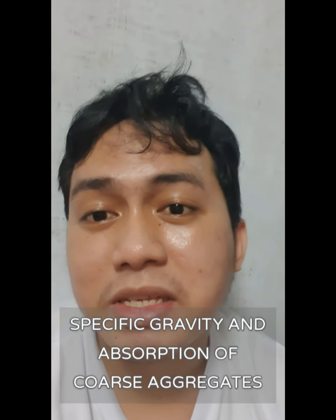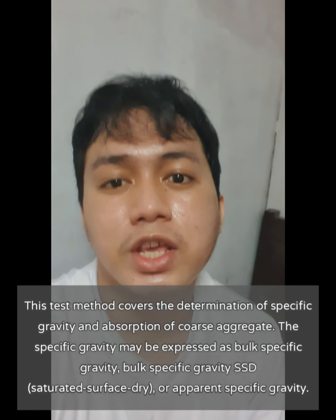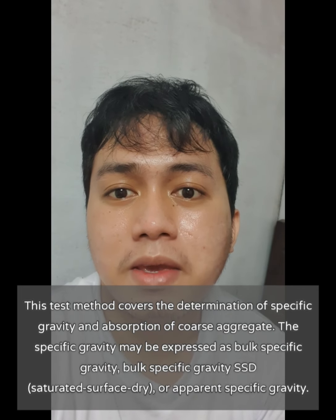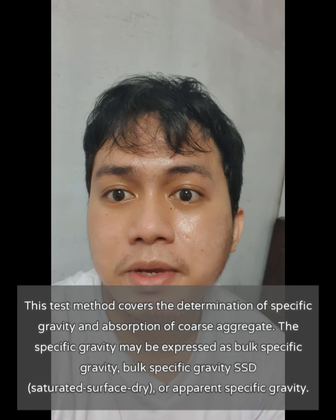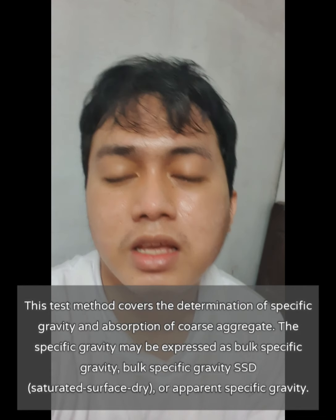Today, we're going to tackle laboratory test number 10, which is the specific gravity and absorption of coarse aggregates. The significance and use of this method is that it covers the determination of specific gravity and absorption of coarse aggregates. The specific gravity may be expressed as bulk specific gravity, SSD, or saturated surface dry, or apparent specific gravity.